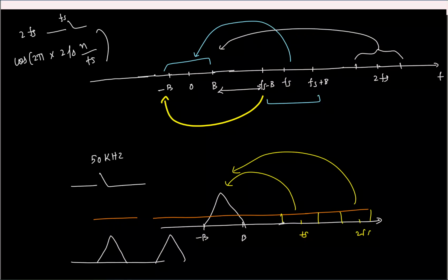No, but see, the actual signal is only this. Analog signal is this. See, your analog signal has a band limited spectrum like this. It is only after sampling that you will have the replicas. When it will alias back also, right? After sampling only you have that, right? See, you have a continuous time signal.